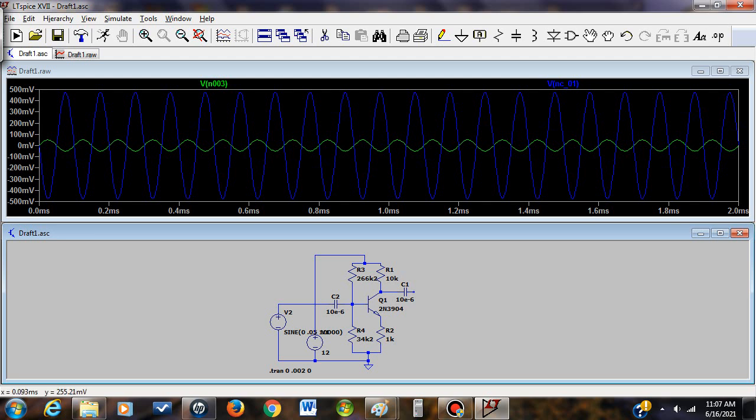And again, we're getting close to about 1 volt peak to peak at the output. Okay, so it hasn't changed all that much. So this amplifier is working as it should, works very properly. And again, I would definitely stick to the value of R2, or your RE I should say, your RE value, which is the resistor at the emitter, of about 1K.